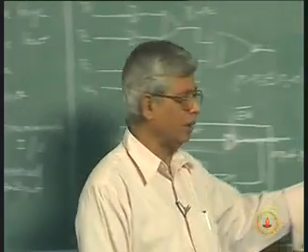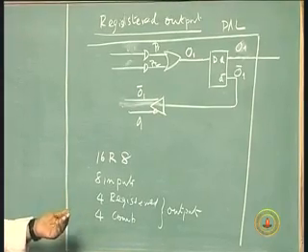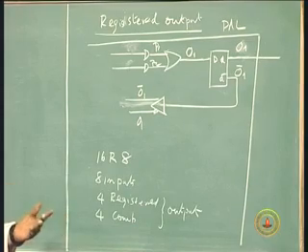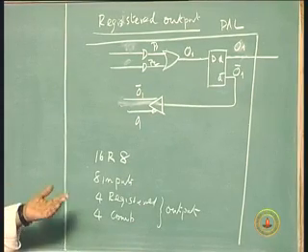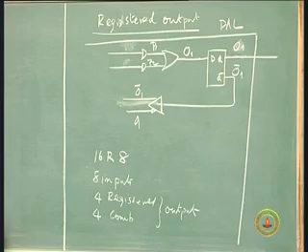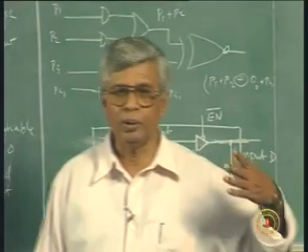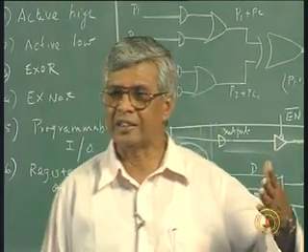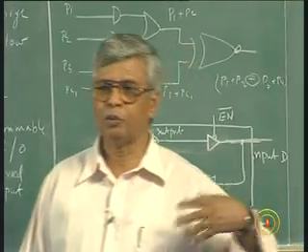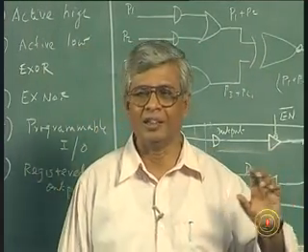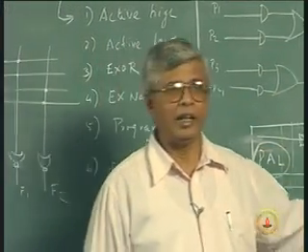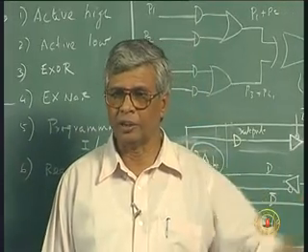You can select an IC with 4 registers, 4 non-registers as outputs. Then 8 inputs can be combined. So up to 4 variables, state variables, you can have 16 states, isn't it? A sequential circuit with up to 16 states can be implemented using a single IC. If you want more, of course, there are 8 registers also available. I'll just give you an example.